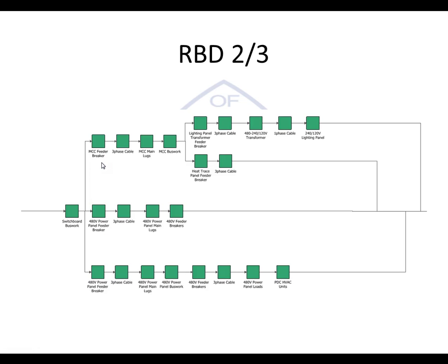An intelligent engineer would distribute all of the loads on the site across many of the options that you have here. For example, the MCC has around 20 starters that you can use for the different loads, and you can distribute your loads across those buckets in order to keep a high reliability, try and keep the site running.